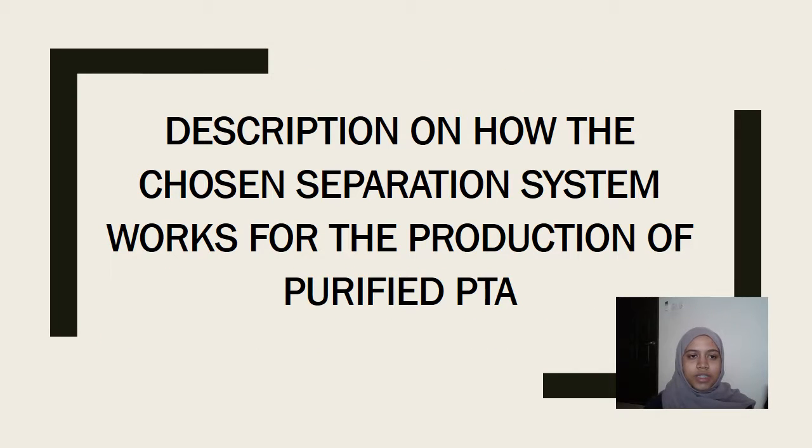I'm going to talk about the description of how the chosen separation system works for the production of purified PTA, including the operating conditions. There are two processes included in this separation system: first, evaporation in order to vaporize all the water, and then crystallization in order to produce purified PTA in solid form.